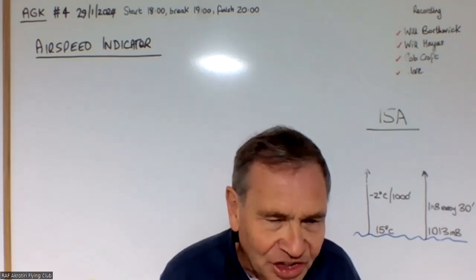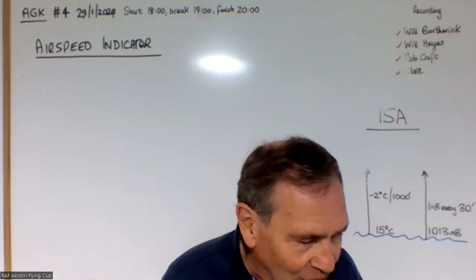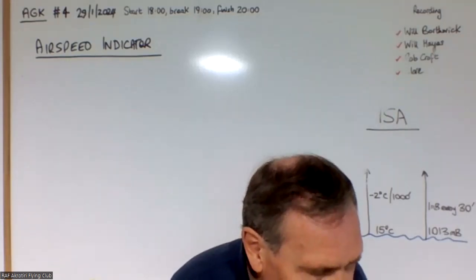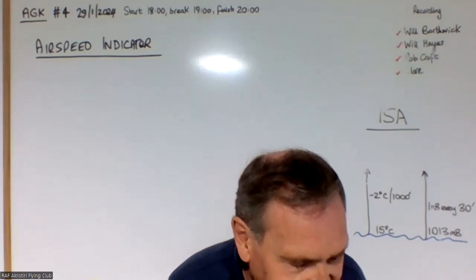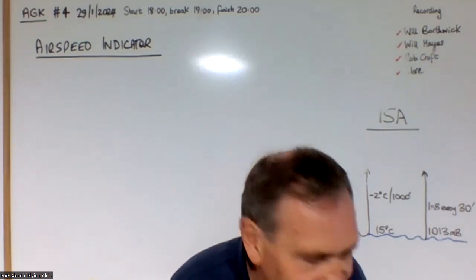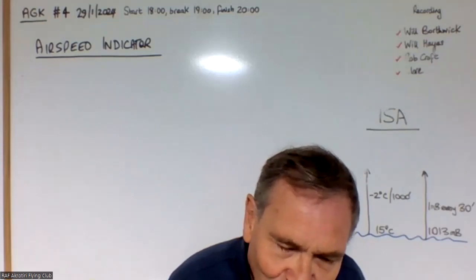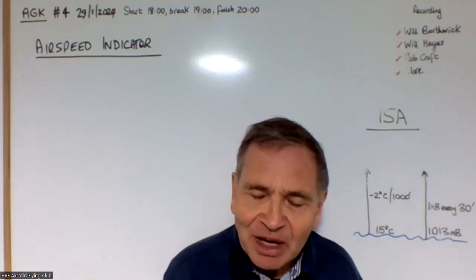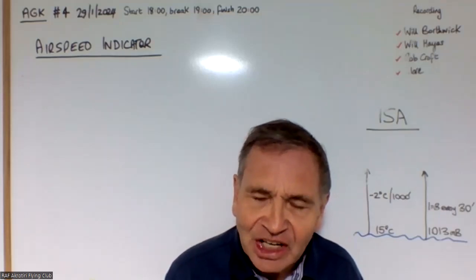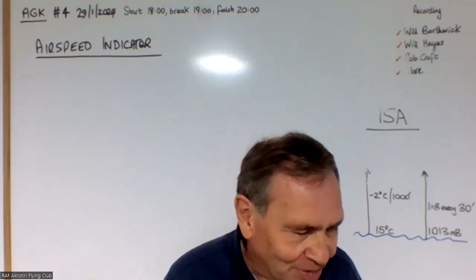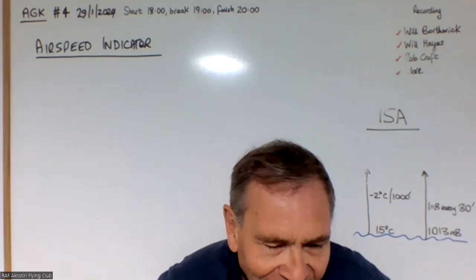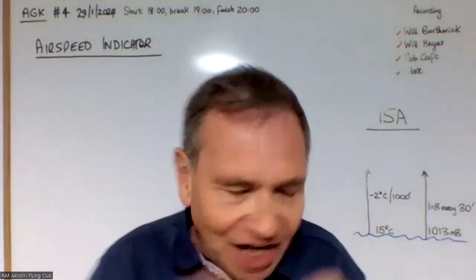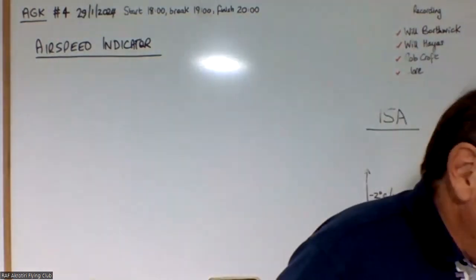It would, but typically what would happen is that let's say that instead of it being completely blocked, more likely it's got stuck by an insect in it. So chances are that the pitot pressure would actually be equal to the static pressure. In other words, it would take like 5 or 10 minutes, but the pressures would actually eventually equalize.